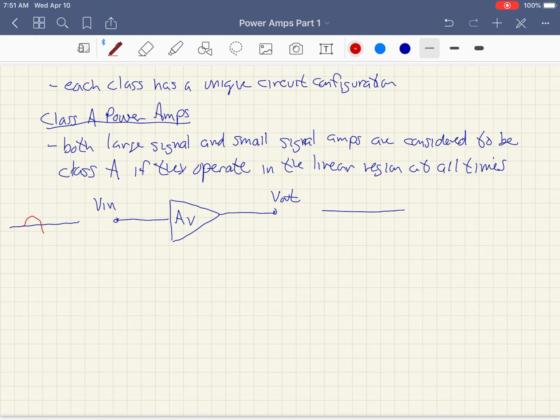Little signal going in, amplified signal coming out. Okay, so we're amplifying voltage. We're not changing frequency. Frequency remains the same. We've got a small input voltage and a larger output voltage, let's say. Okay, there's no distortion, there's no clipping. Basically, you've got a sine wave that's at a higher amplitude coming out than what was put in.